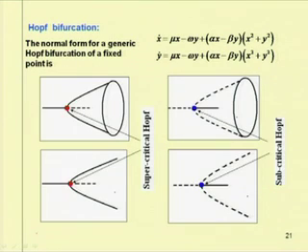Similarly, one can have the Hopf bifurcation, in which the fixed point response becomes a periodic response after the bifurcation. If from a stable trivial response it becomes a stable periodic response, then this is known as a supercritical Hopf bifurcation.